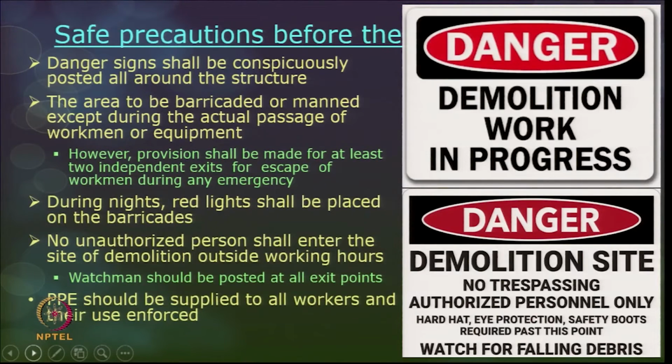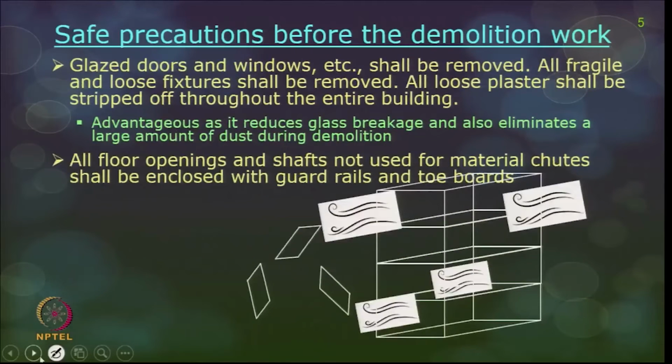And the walkways and passageways should be provided for use of workmen, who should also be instructed how to use the walkways and passageways. And these walkways and passageways should be well lit, there should be proper illumination, they should be inspected, and they should always be free from debris for the quick movement of material and workers. All nails in any form of lumber should be withdrawn, hammered, and they should be removed from the site if there are loose planks, and they should be piled up for further cleaning and burning.